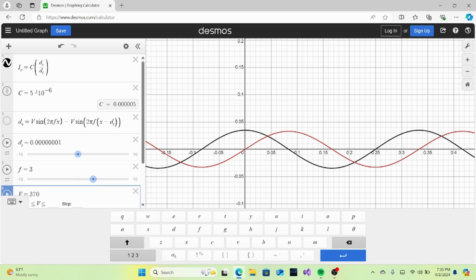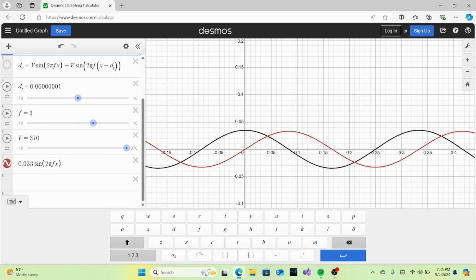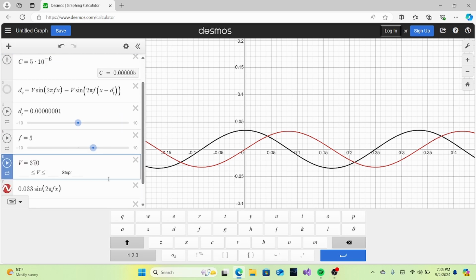What we'll do is, say we have a condenser fan for an air conditioner. Most of those take a 5 microfarad capacitor. And most of them, when they're functioning properly, generally draw about 0.7 amps, and the capacitor that's attached to them has about 370 volts across it.